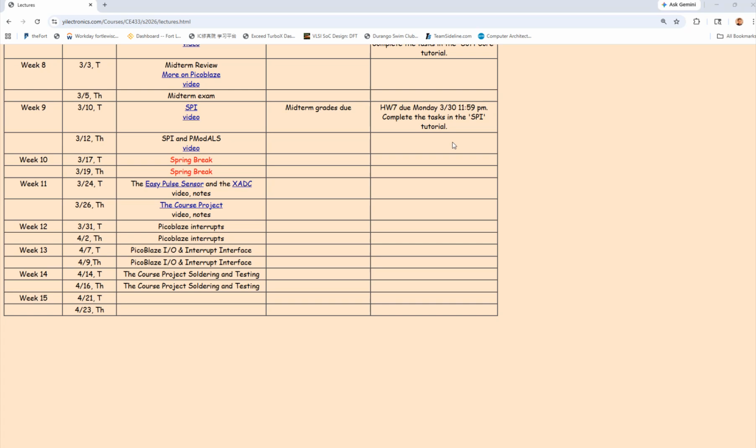From scratch, right, from the very beginning, what's the first thing you need to do? Usually, filter, sample it, filter. Filter, yes. So all these analog signals have an undesired DC offset, so you need to remove that first. So usually the first stage is going to be a high pass filter. I have a capacitor at the very front stage, and you filter that out.